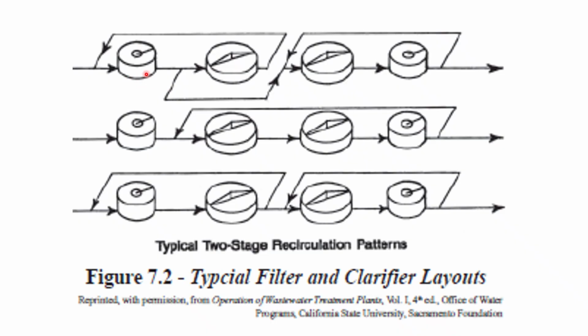You can get pretty complex here though when you think about it. Here's your primary clarifier, here's your trickling filter, second trickling filter, and then your secondary clarifier. So what we can do is we've got influent coming to the primary clarifier, the heavier organics and inorganics settle out, send it to the secondary or to the trickling filter. We can also split it off and send it into another trickling filter. But take a look at the first trickling filter. We're recirculating it, and it's going to go through the primary clarifier again.